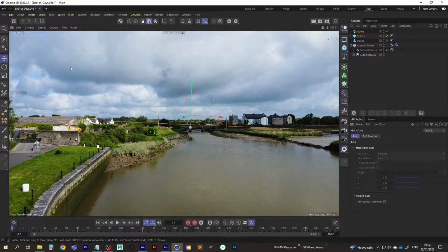We can do it moving that up a lot more. And as the first anchor point is here, we want it to be out of the shot. So I'm just going to click and drag. Something else we can do to get our axis handle closer to our spline is enable axis mode, bring that down, and then disable axis mode. Now our axis handles are much closer to our spline. That makes it a bit easier.